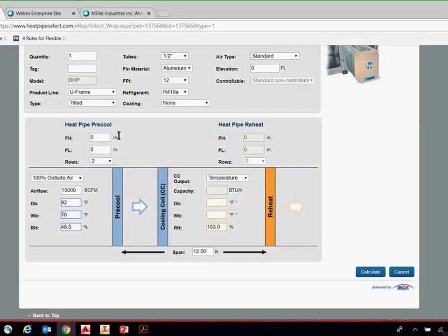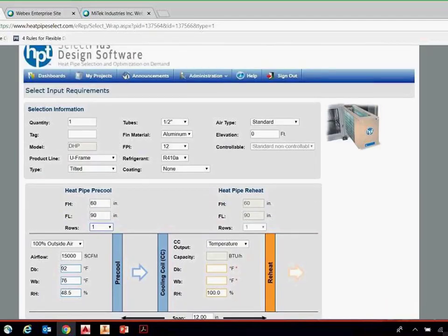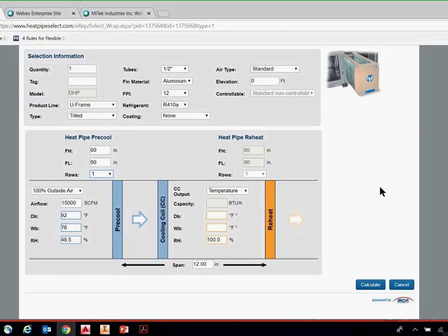And going back up top now, sorry for jumping around a little bit. I just wanted to show you this mixture calculator really, but jumping back into the actual dimensions, I sized the unit, this example, at 400 feet per minute, which is typically what we see, or I guess maybe the sweet spot for wraparounds, best bang for your buck. Fin height, again, sized for 400 feet per minute. I went with 60 by 90. And let's start with one row, just to see what that gets us.